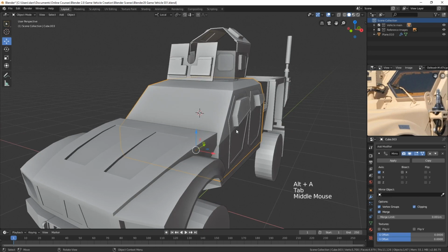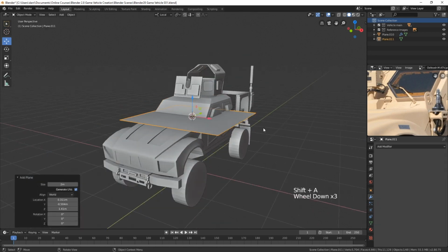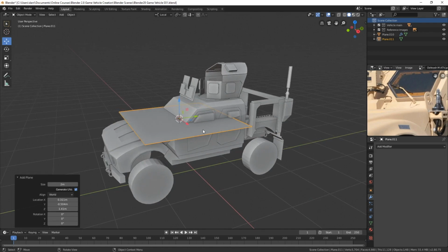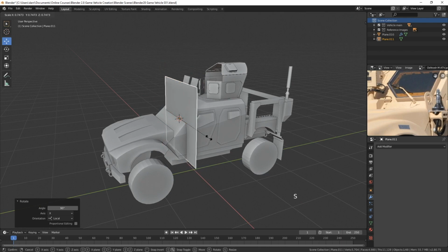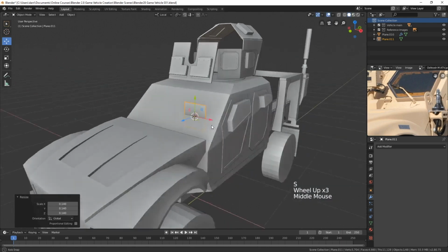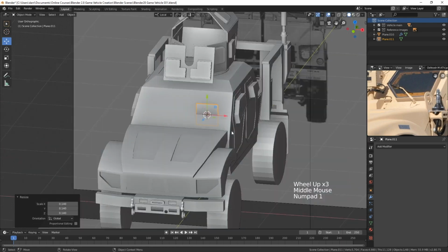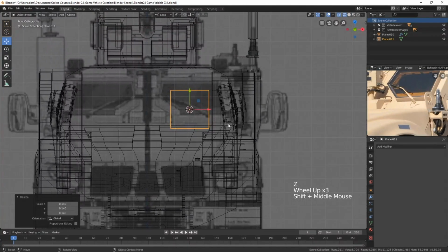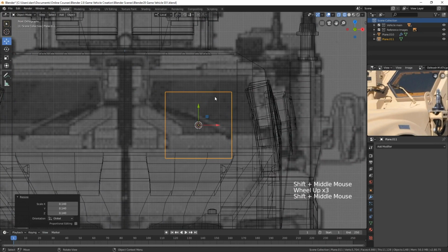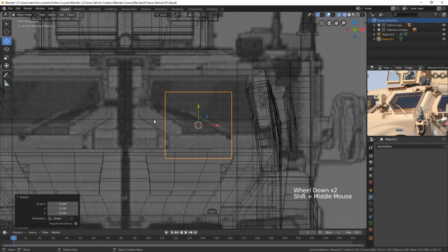Now let's go ahead and create a polygon plane with Shift A, mesh plane. Here we go. I'll turn it in the x-axis with RX90. There we go. And I'll scale it down. And at least for now, I'm going to go to the front view, and let's go to wireframe here. I want to make this about the right shape before we tilt it, and then we're going to adjust the edges once we tilt it. But at least for now, let's see what we can do here.